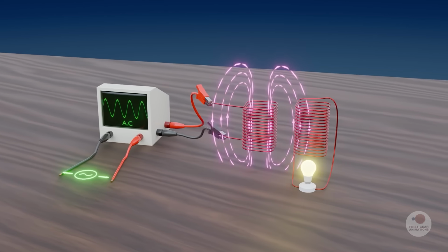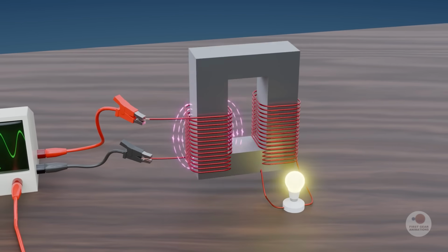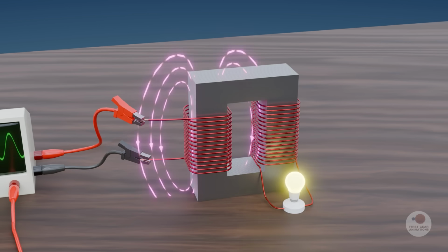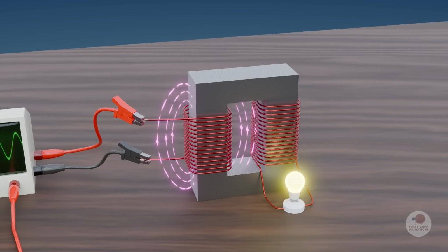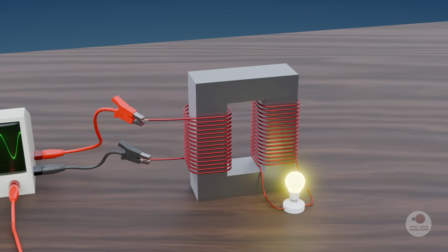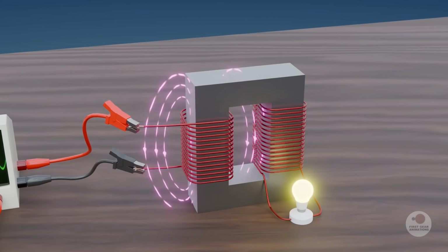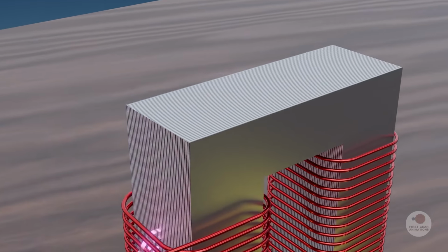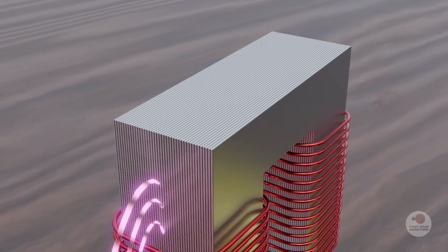To ensure the magnetic energy isn't wasted, we place a loop of ferromagnetic material, like laminated iron, between the coils. This core acts as a low reluctance path, perfectly linking the magnetic flux from the primary to the secondary winding. To maximize efficiency, the iron core isn't a solid block. Instead, it's constructed from thin sheets of iron, stacked together and meticulously insulated from one another.